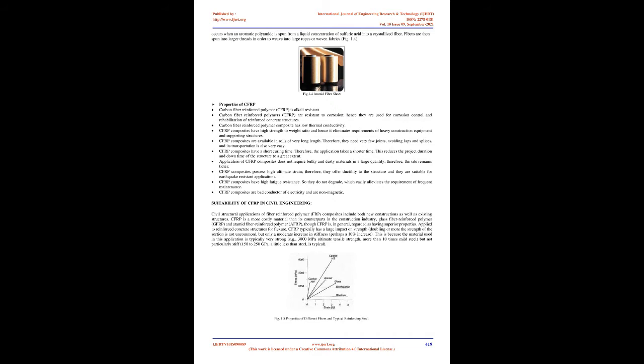The high strength-to-weight ratio, immunity to corrosion and easy handling and installation has made FRP jackets the material of choice in an increasingly large number of projects where increased strength or inelastic deformation capacity must be achieved for seismic retrofitting, despite the relatively high material costs.